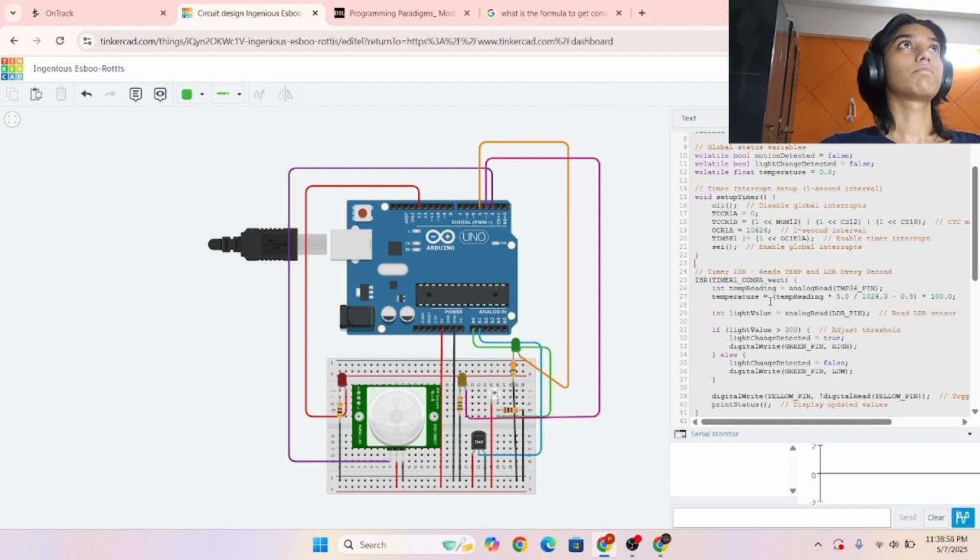For example, 1024 is one prescaler value. So the overall cycle is divided into smaller chunks. That's what we do. And then if that particular oscillation value arises, we do some sort of interrupt, like clearing that value and stopping something else.